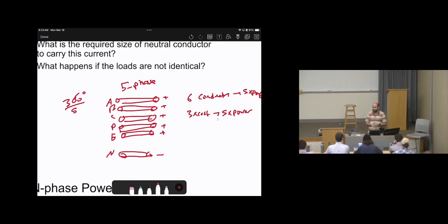So we realized, okay, five phase can provide higher power, but in overall cost, three phase will be cheaper. So the benefits that we will have from five phases will not be significant. And the same thing applies when we build transformers: building transformers based on five phases requires a very large size transformer, and this will be a big challenge. So in summary, theoretically, five phases is better than three phases. But practically, unfortunately, we cannot do that, which is very expensive.